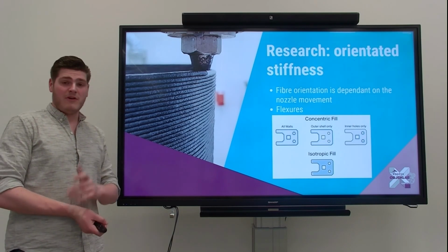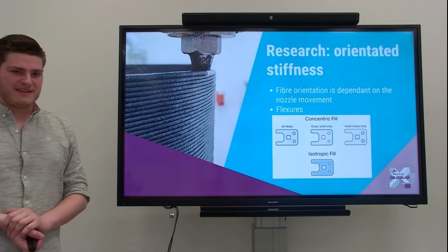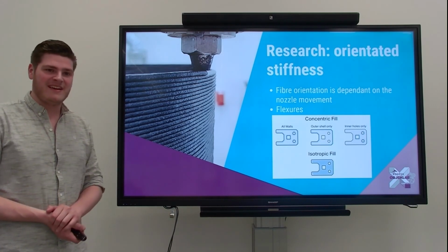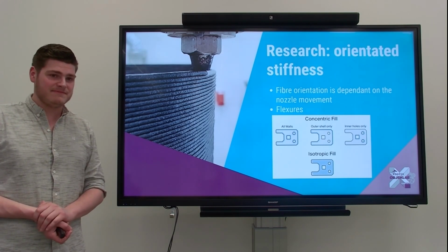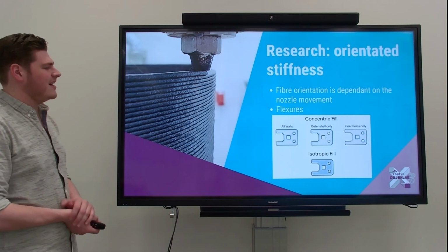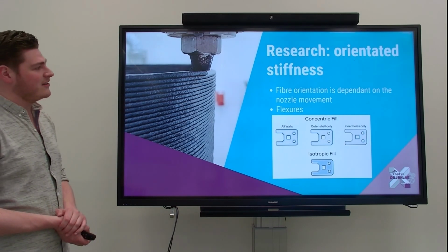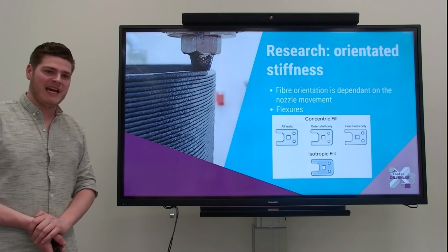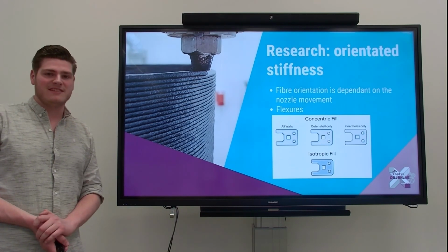So we can make more hinge-like structures in just the design of your part. You can create flexures in a single piece where you normally would use a hinge. By using all these complex new structures and design strategies, and by getting to know the process that we're using, we will be able to create even more interesting and complex designs.